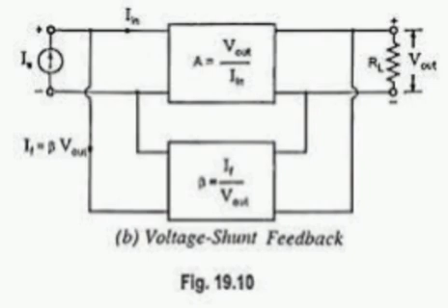Classification of power amplifiers. Class A operation. Transistor operates in active region at all times. Collector current flows for 360 degrees of the AC cycle. Unloaded voltage gain of CE amplifier A equal to minus RC by RE dash. Loaded voltage gain AV equal to minus RC by RE dash. Current gain of the transistor AI equal to IC by IB, where AI equal to current gain, IC equal to AC collector current, IB equal to AC base current.